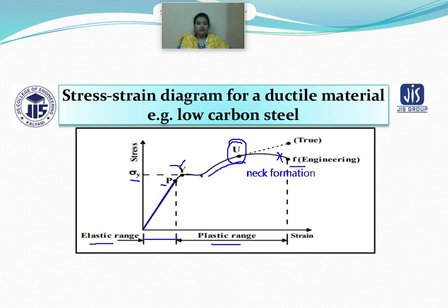Why is this neck formation? Because if I talk about this, it will occur only for ductile material. Please keep in mind, neck formation will obviously occur for ductile material, because whenever you implement load, it will create a tearing in nature. Before tearing, a neck formation will occur, and this neck formation will further break at your breaking point. So this is the failure, none other than your breaking point.